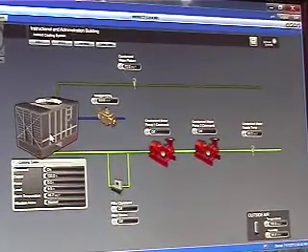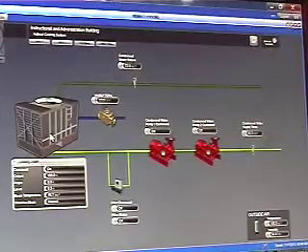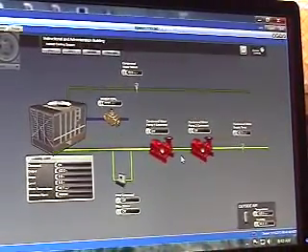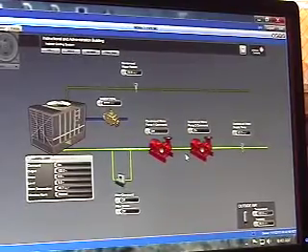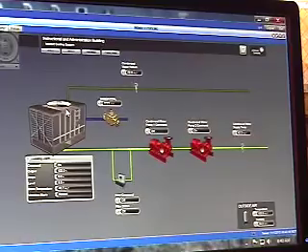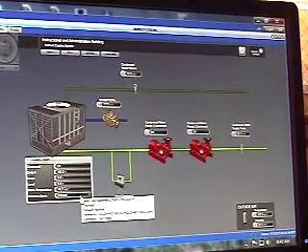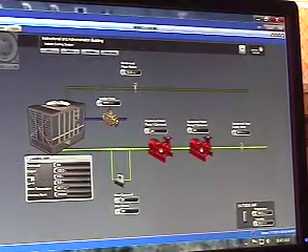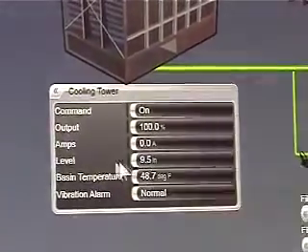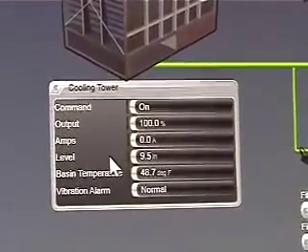For the cooling tower, we're trying to maintain a condenser water supply temperature of about 50 degrees, this one right here. So when we turn this on, these are just constant volume pumps, they run, and the cooling tower fan then modulates up and down to maintain a condenser water temperature. Same thing, you also have a current draw here. There's a level sensor here that gives you the ability to read what the level of the tower is, but it's not a controlling sensor. We're using it for monitoring and alarming, but not for actually controlling the level.